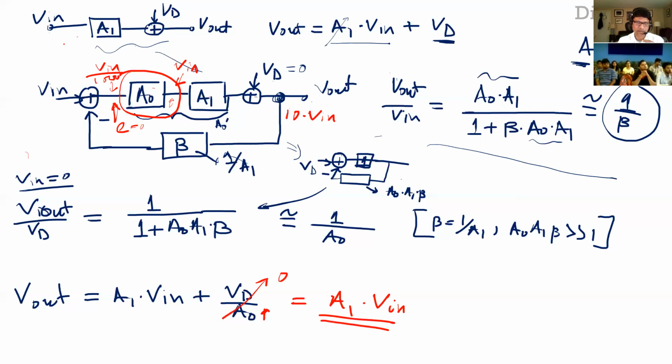For example, here in the open loop case, you saw the total V in. So let's say you had an audio amplifier and the input was 100 millivolts. You would see the 100 millivolts straight here. But in case of the feedback, if you had a gain of 1000 here or 10,000 here, you would see only a microvolt here. So if you have only a microvolt, then your linearized model is still valid, right? And that's why we can still use those linearized models, because of feedback. If it was open loop, then you'd be distorting heavily. Okay.